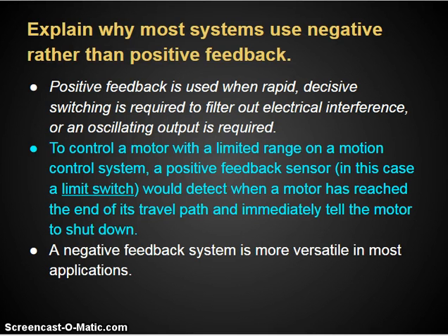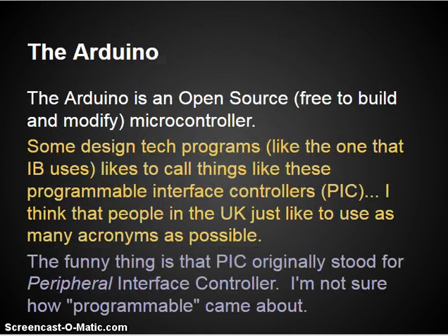The way that works is when it gets to the maximum travel of the distance, the carriage physically hit a switch. And what that did was that prevented it from going any further in that direction. And in the other direction, the carriage hit another switch so it wouldn't go any further in the opposite direction. So that is a feedback loop to prevent it from overextending and falling apart. Because if that had not been done, the screw would have pushed the linear actuator right out and the whole thing would have fallen apart.